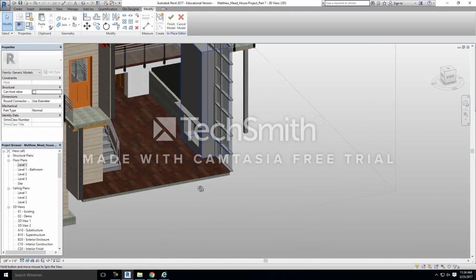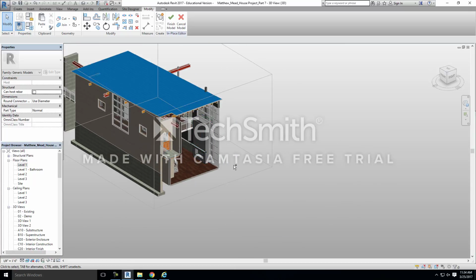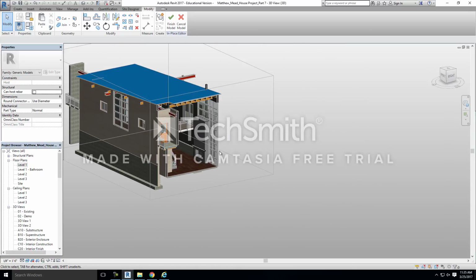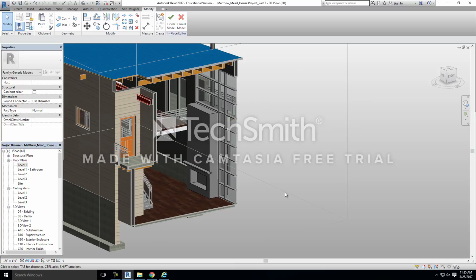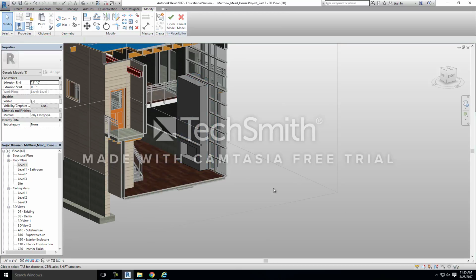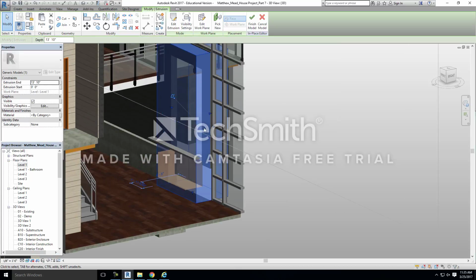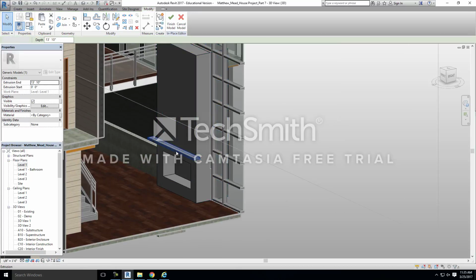All right. And lastly, so we kind of have the basic shape of it. It's a very basic fireplace, nothing too special about this. But what are we kind of missing right now? What could we add to this fireplace that would give it a lot more? Texture. Yeah, absolutely. We need to add some texture to it. So what I'm going to do is I'm going to click on the original extrusion, and notice that if you go through and you click on all the different extrusions except for the void, you can add a material to them. Okay, so you can add a different material to every extrusion that you create.